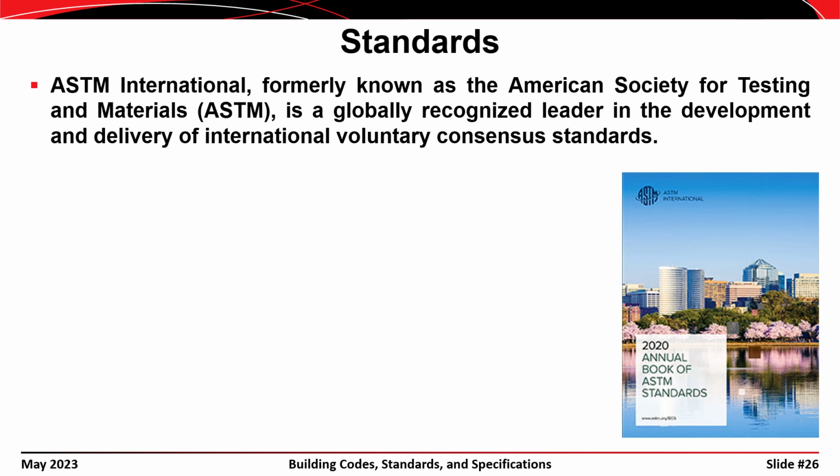The idea is that a structural engineer doesn't have time to be an expert in all facets of engineering. He doesn't have time to be an expert in metallurgy, but he or she does need to ensure that the steel that they use on a project is of a high quality and has sufficient strength, stiffness, and ductility to suit the needs. All he or she needs to do is specify in the construction documents that ASTM A36 steel shall be used, and then the contractor is required to use a steel from a mill that conforms to the A36 standard. The committee members that wrote the A36 standard are the metallurgists, not the structural engineer.